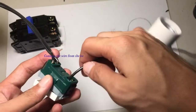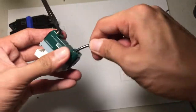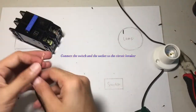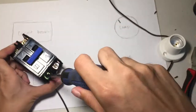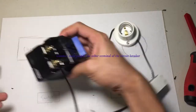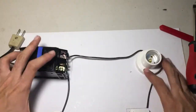Connect the wire from the bulb socket to the common terminal of the switch labeled 0. Next, connect the switch and the socket to the circuit breaker. Secure the screws in the circuit breaker to keep the wires connected to it. Connect a male plug to the other terminals of the circuit breaker. The circuit is done and it is now ready for testing.